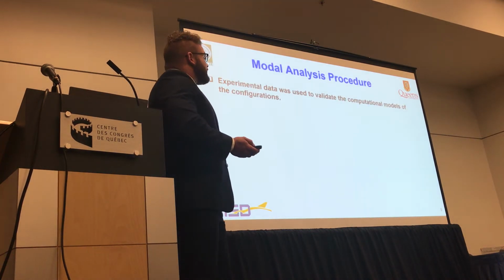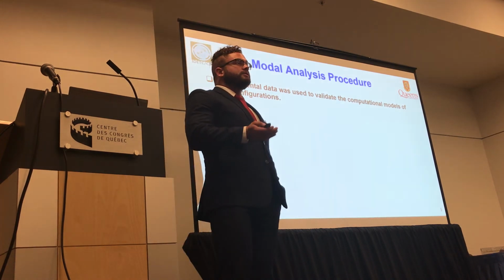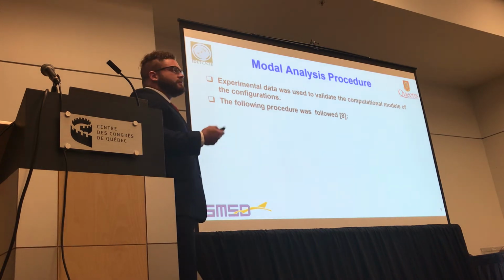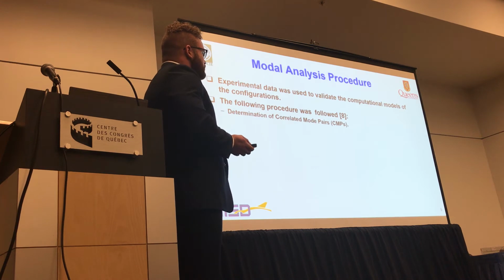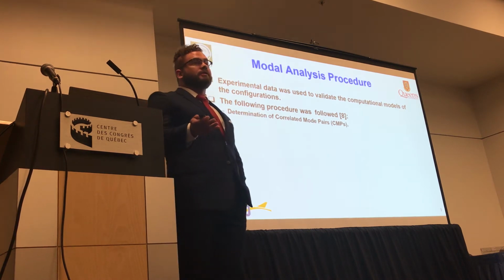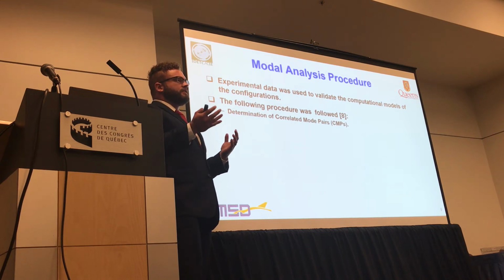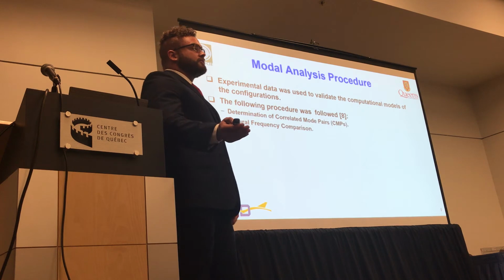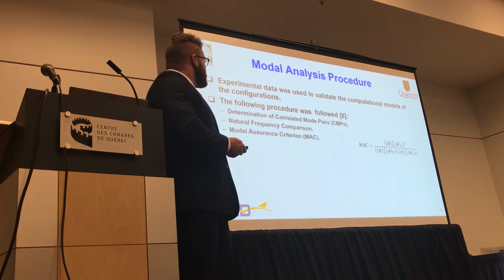So for the modal analysis procedure, I first collected experimental data used to validate a computational model. The following procedure was followed. It's just the standard model correlation techniques of first determining the correlated mode pairs, which is just qualitatively which mode shapes physically match up and look similar. Then I performed a natural frequency comparison of the correlated mode pairs using a linear regression.